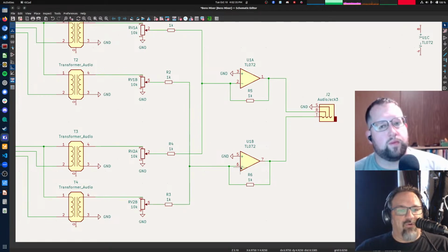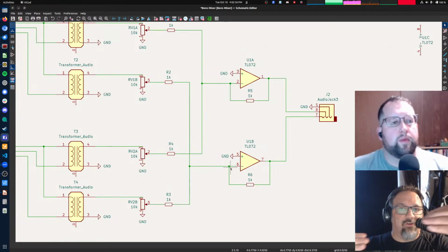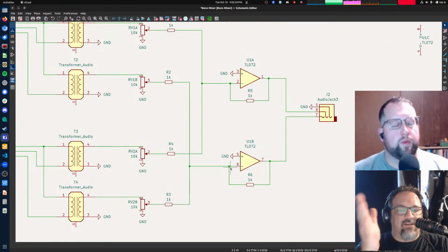And so what you end up with is what's called a summing amplifier. We are going to sum, as in add, all the currents coming from this input through this resistor to ground, which is what this terminal is, and whatever current comes in through this input, through this resistor, to ground. And all of those currents are going to get summed together and forced through this one resistor and create a voltage on the other side.